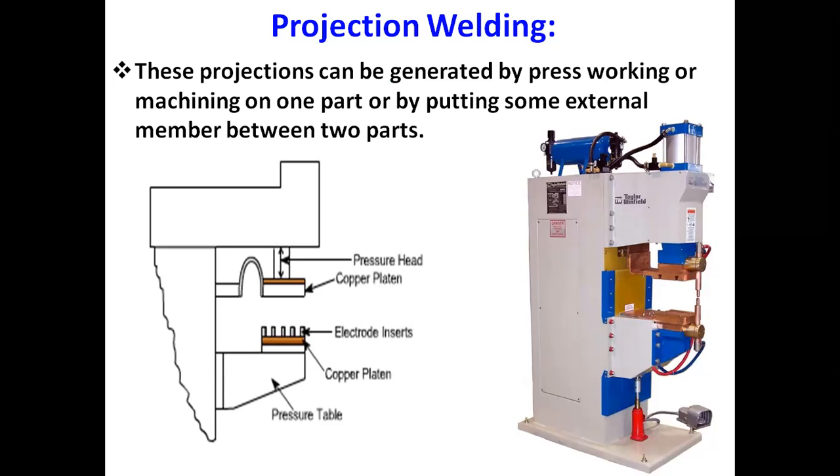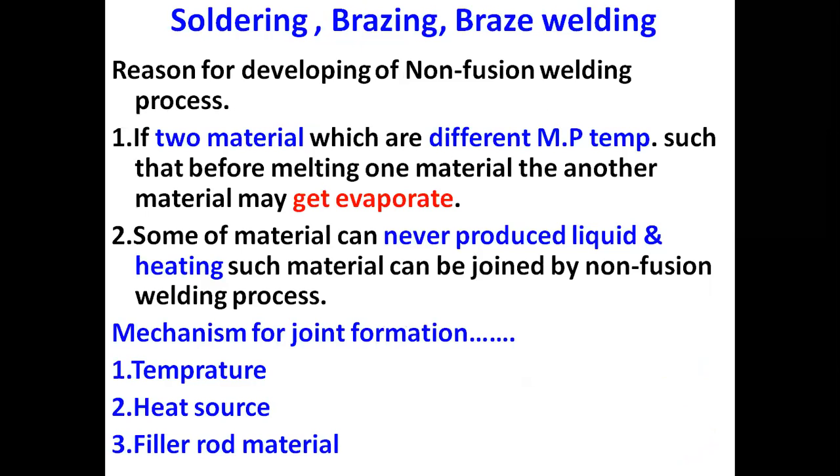And the last one, that is destructive testing. Here, whatever the weld is, that weld is destroyed in testing, and mechanical tests are done for tension, compression, shear, which are performed on the weld joint. Metallurgical tests for microstructure defects, heat affected zone, etc., are performed on the welded joint. So these are the three inspection methods. Now let us see the next, soldering.